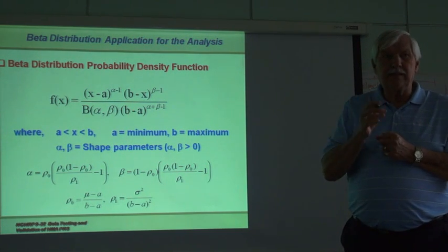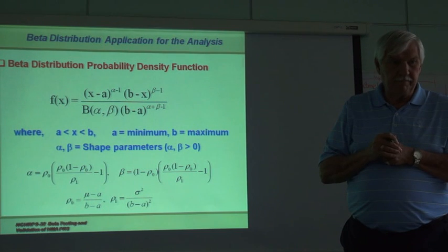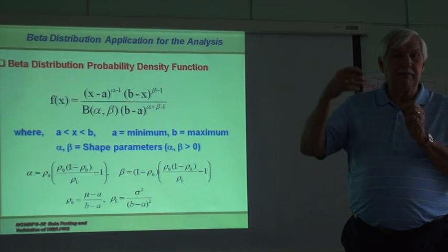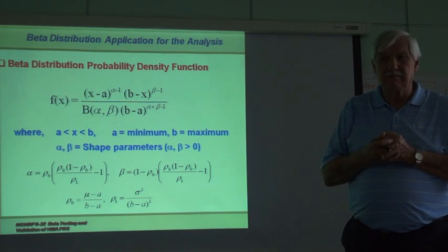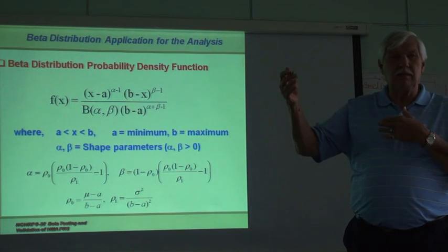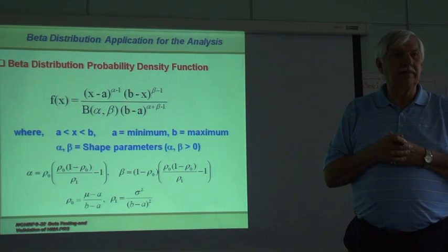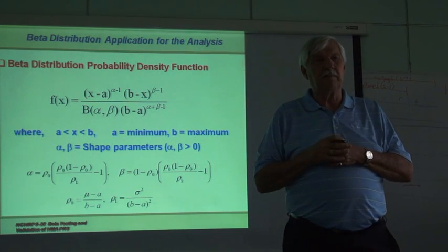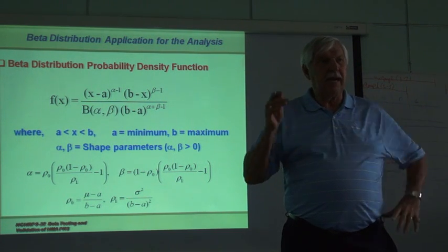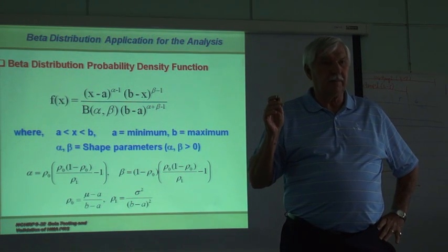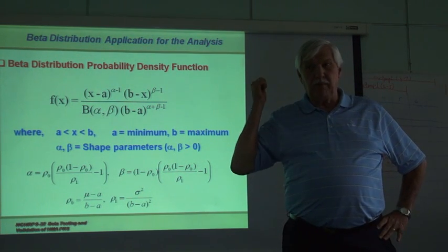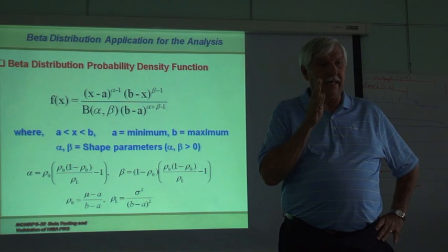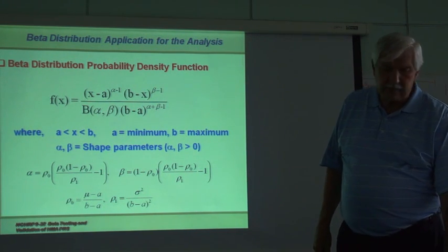So what is the maximum value of the cracking that I can have in the MEPDG? It's going to be 2 times 5,280. I can never go above 10,560. We have the same kind of limit that we apply for thermal cracking. So you see, I could never do this in a normal probability distribution, but we put limits on cracking and I can control the minimum and maximum.